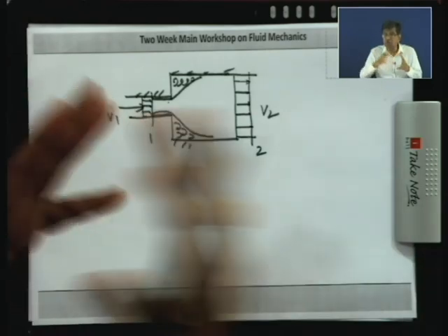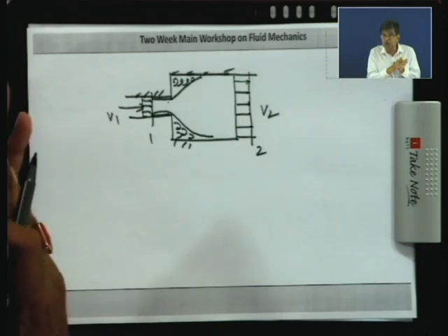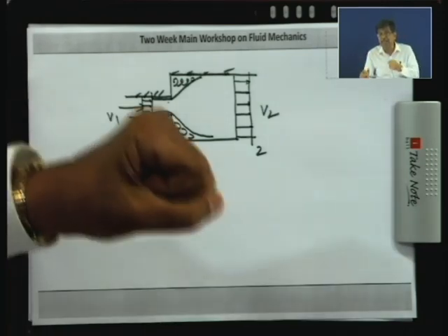In many situations, flow through a diffuser goes from a lower pressure to a higher pressure. We know fluid flows from a higher pressure to a lower pressure, but it flows from a higher energy to a lower energy. So the energy gradient makes it flow, that means kinetic energy is counteracting the adverse pressure gradient. But fluid particles lose kinetic energy near the wall because of the boundary layer, because of the momentum interaction between the fluid and the wall. The fluid comes to rest at the wall.